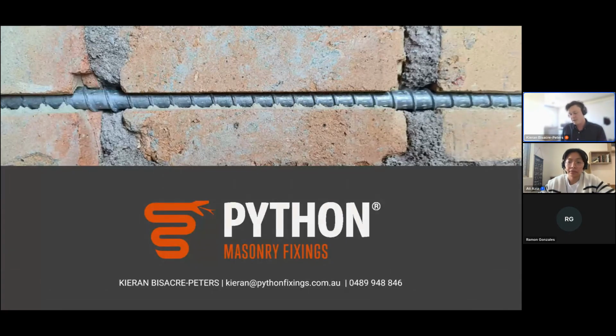Good question, Jesse. So it comes down to the engineer's QA essentially, but what is typically done is, the beauty of having a mechanical screw anchor means it's reversible. So it's very easy to implement a plan for inspecting them every 10 or 20 years. You could actually unscrew the ties and inspect them. And if they do have any signs of corrosion, which I wouldn't expect, you could take them out and replace them very easily.